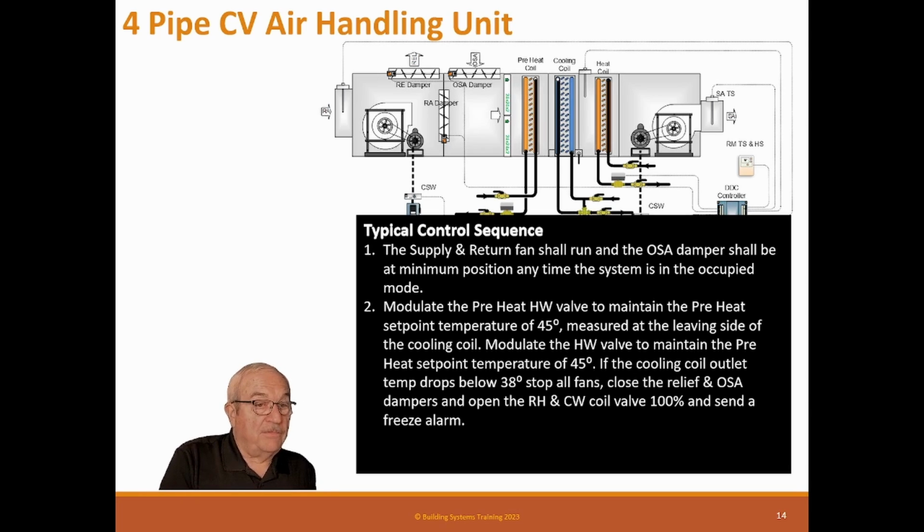This is designed for a cold country where it might be minus 10 outside, and you're bringing some outside air in that's made the inlet air too cold. So this preheat coil is preheating things up. This sensor right here is a sensor that passes the cooling coil. If it senses air below 40 degrees, it's going to do a freeze.